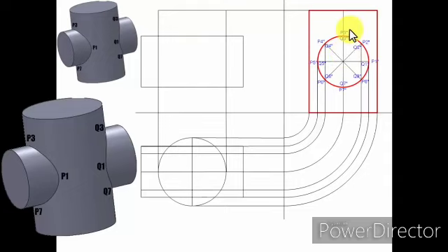Okay, so they're gonna be worked out from this side view over to this top view. Let us see how that can be done. I'm gonna be shifting all these points over here. So this curve of penetration is for P and this curve of penetration is for Q. How can that be worked out? Please watch this carefully. We start from looking at this entire scenario from the top. You're going to see this point P1. It is far away from the vertical plane, from this XY line in fact.